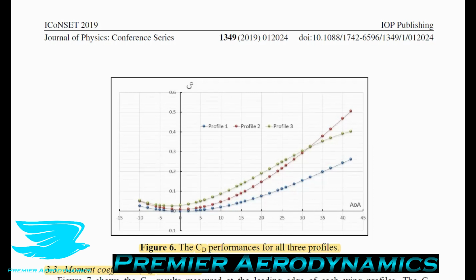So that's very low. I looked up the drag coefficient of a NACA 0006, which is a very thin airfoil, and it's the closest one in some respects to these airfoils, particularly profile 1. And the drag coefficient was still like 0.005. So it's still much higher than what they're reporting here. So I would be tentative about this value here, and I'd like to look into it more.